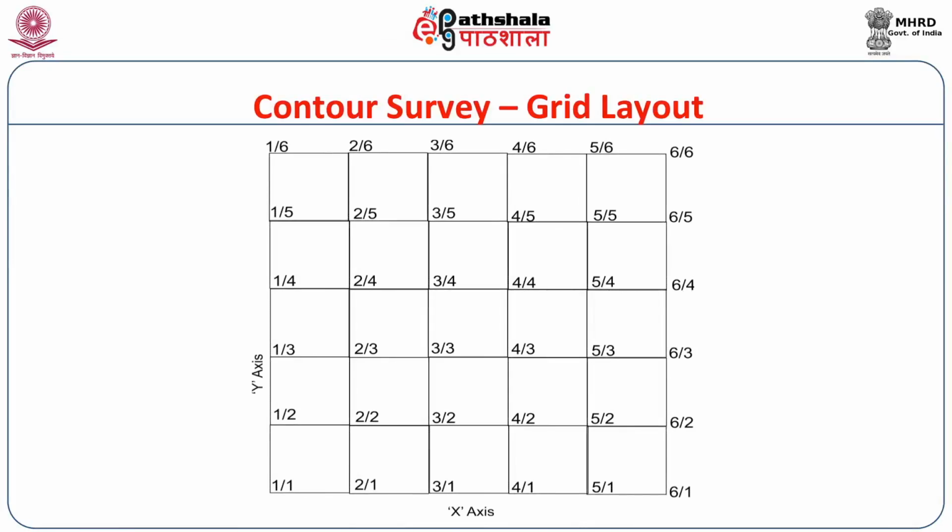Before starting the survey, we have to prepare the site by first removing all the seasonal vegetation on the site, and then we have to prepare a grid sheet, contour survey grid sheet, and the same numbers in the grid sheet will be used to make the layout on the site. So, usually the layout is done in east and west axis and north and south axis.